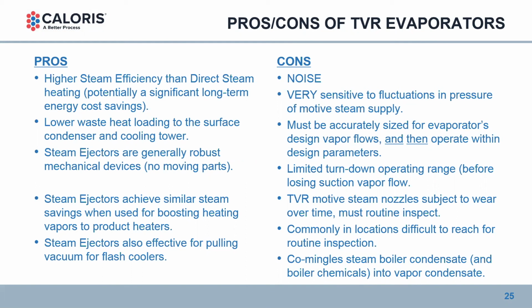And in one particular product case where there are some non-volatile gases coming off the system, we've actually found it's more energy efficient and cheaper in capital cost to use a steam ejector to create the vacuum on the system altogether rather than using a liquid ring vacuum pump.